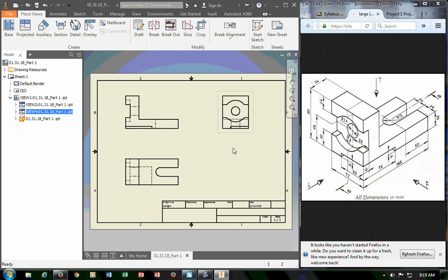I would agree with that statement as well, and it would look like this. Okay? This is correct. This is your front view, this is your left side view, and this is your top view. That's what the customer wants to see. They made a point of pointing at this, so that's fine. Cool? It is represented again in this drawing in what's called first angle projection.